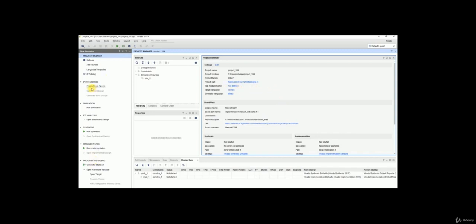The second option which we will require is the IP integrator. Throughout the course, we will be majorly focusing on the IP integrator, which provides us an option to work on IPs and the block design. Okay, so the connection canvas helps to accelerate the design of an embedded system. Below the IP integrator, you also have simulation, right? So simulation, RTL analysis, synthesis, implementation, everything can be used for either a pure RTL design or an embedded